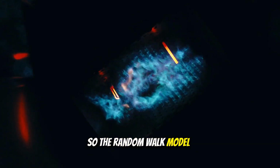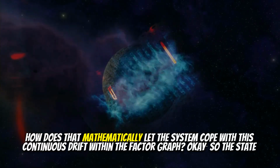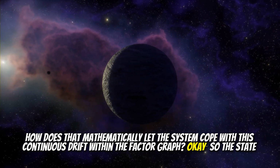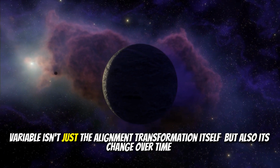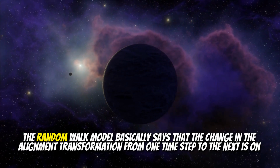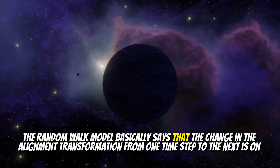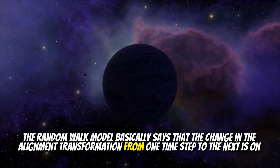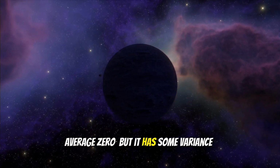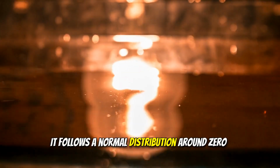So the random walk model, how does that mathematically let the system cope with this continuous drift within the factor graph? Okay, so the state variable isn't just the alignment transformation itself, but also its change over time. The random walk model basically says that the change in the alignment transformation from one time step to the next is, on average, 0, but it has some variance. It follows a normal distribution around 0.